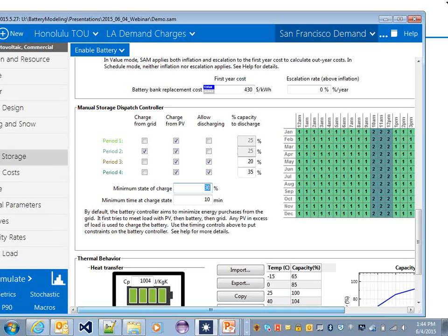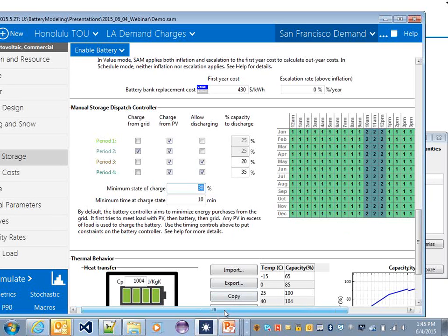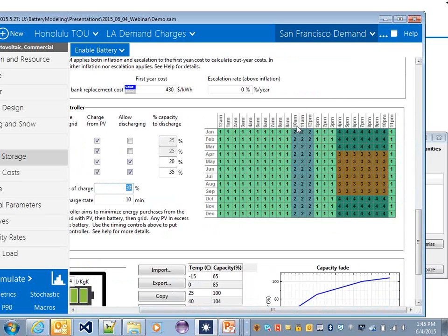I have a question about sub-hourly. Can you remind me, can you do sub-hourly PV simulations? You can. And then the battery too, so if you had a 15-minute peak to full charge, you capture that. Yeah, you can enter up to 1 minute data for a weather file. Right now, the battery model will run at that time step as well. The only limiting factor would be these hour schedules. So you can't choose a sub-hourly dispatch strategy at this point. So that would be the limiting factor.